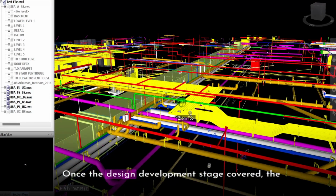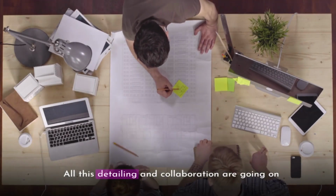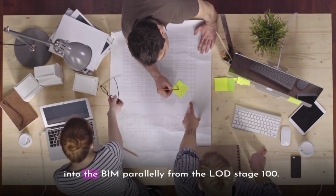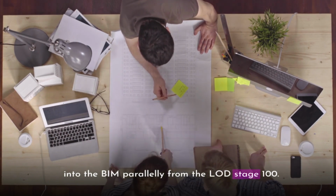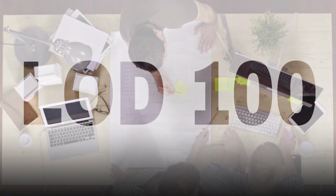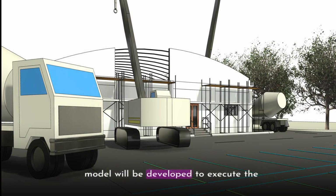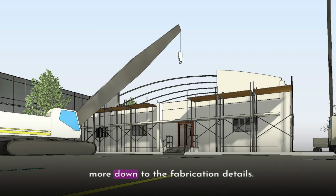Once the design development stage is covered, the construction model begins to play a crucial role. All this detailing and collaboration has been going on in BIM parallelly from LOD stage 100, meaning from the conceptual design itself. At the stage of LOD 400, a construction model will be developed to execute the construction activities and installation process of the construction elements, with more down-to-the-fabrication details.